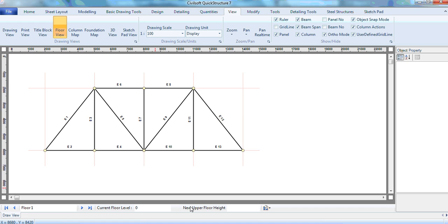The next, of course, is to create the elements. Now we have a few quick ways of creating the elements that can make it a little bit easier when you want to connect the elements, to minimize mistakes. If I want, I can take the vertical members first, or I can take the horizontal members first, then later the verticals, or usually you can take the top chord, the bottom chord, then the verticals. Then later you can connect the internal ones. Fine, let's take the bottom chord first.